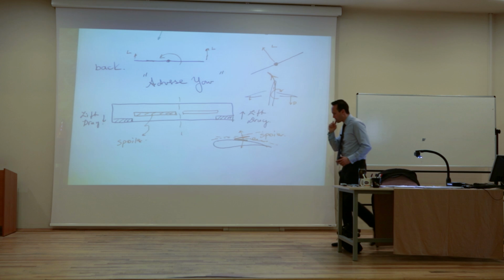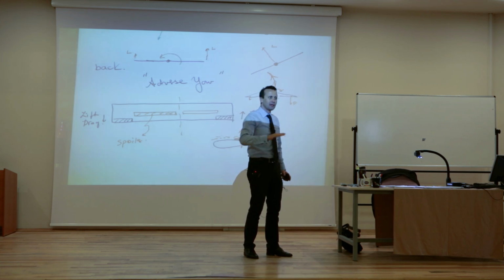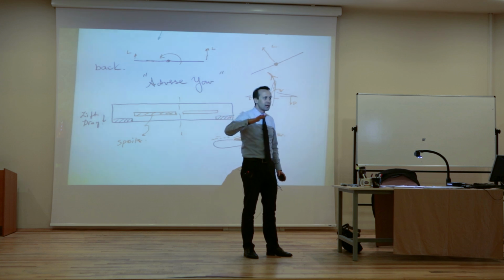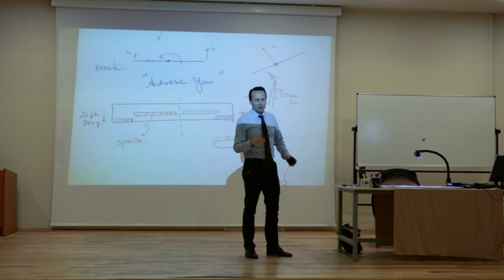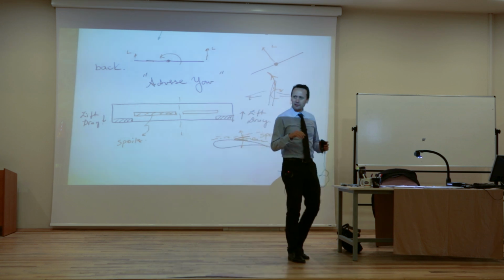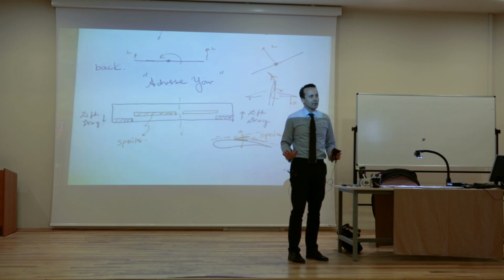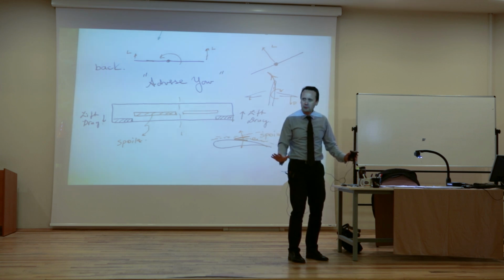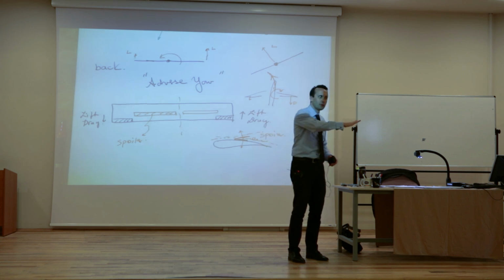Okay, one more thing. A lot of times when pilots land the aircraft, and the pilot makes a really soft landing, passengers are very happy. They always say, "Oh, that's such a good pilot, because we made such a soft landing." Well, it's not really the best way to land. The best way to land is to really smash the airplane onto the ground very firmly. Open your spoilers so that you don't take off anymore.